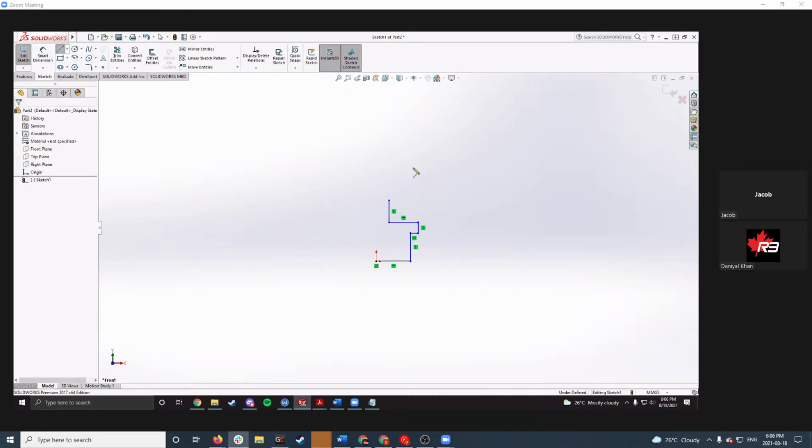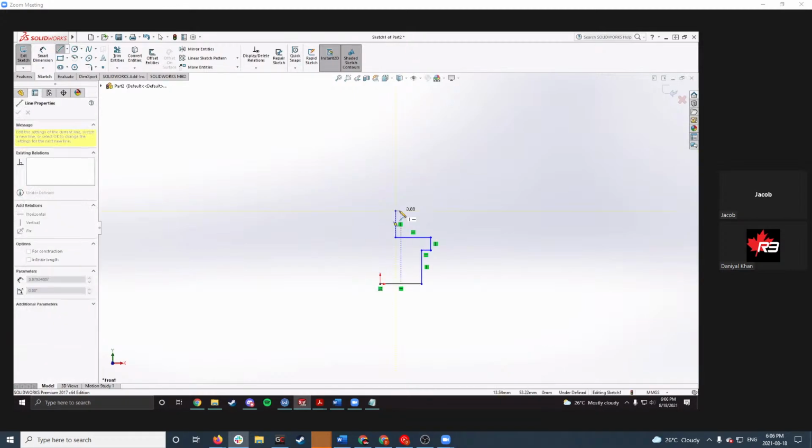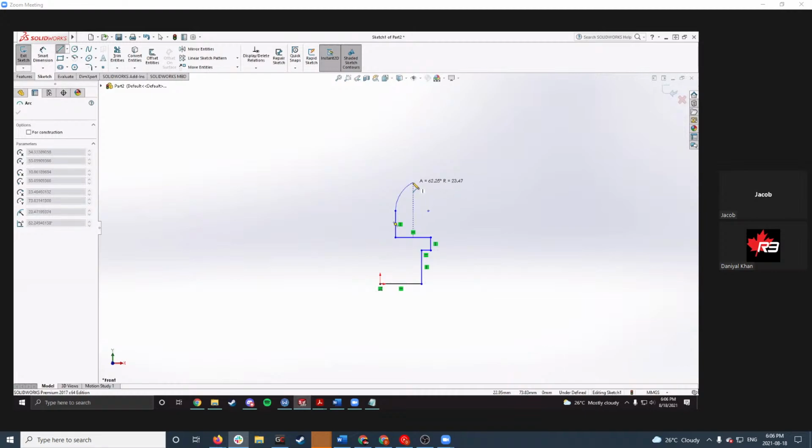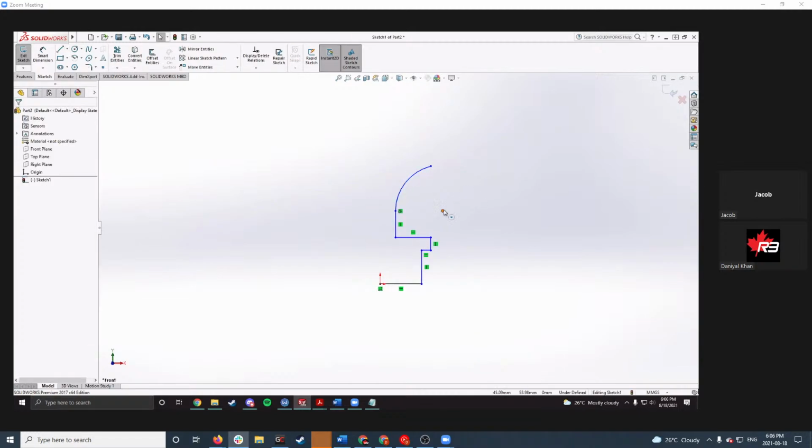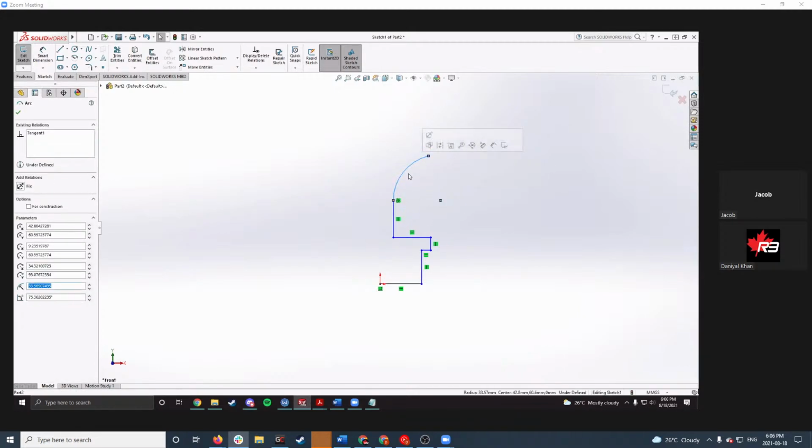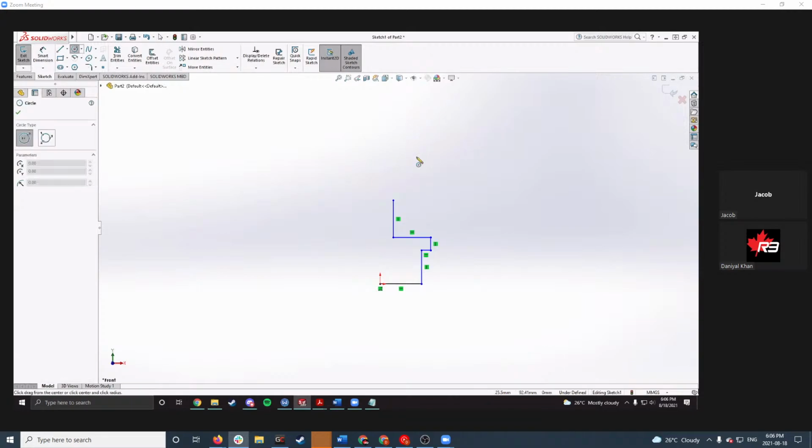Basically, with the line tool selected, when you draw from a point, it'll make a straight line. But if you go back and hover over that point again, and you see this yellow circle next to the pencil icon, and then you start drawing again, it'll make a curve based on where your mouse is. So I'm just gonna select that here, and it's an arc of a circle that you can move around. Obviously, the other way to do it is to select the circle tool and draw a circle.